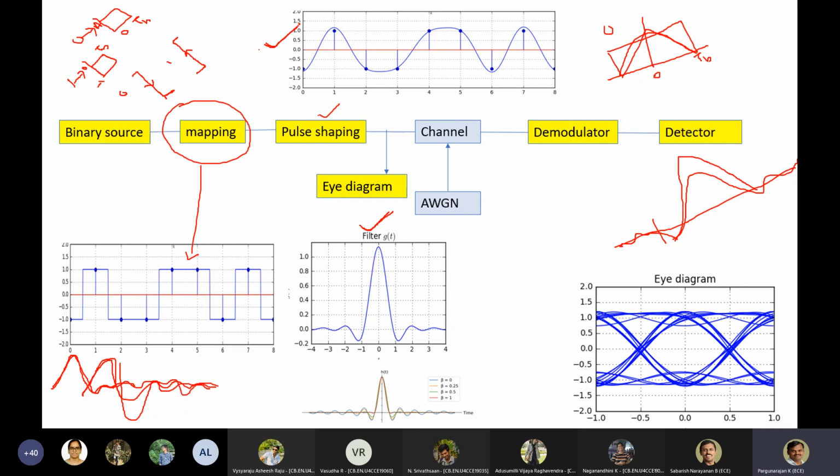So this is at the transmitter side. I made my signal band limited. The advantage of this technique is that it is going to limit our signal to comply with the FCC. For this particular application, only this particular bandwidth is allocated. So I decided to make my signal available within the band limit. Here we are facing some set of problems. Because of this effect, the symbol rate is reduced somewhat. That we studied in the theory part. At present, I don't want to introduce it here. Anyhow, we are doing the pulse shaping.